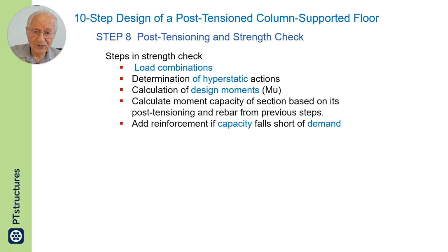So post-tensioning and minimum rebar provide some capacity, and design based on ACI are such that in many cases, I would say in most cases, the capacity is more than demand. So we let it be.